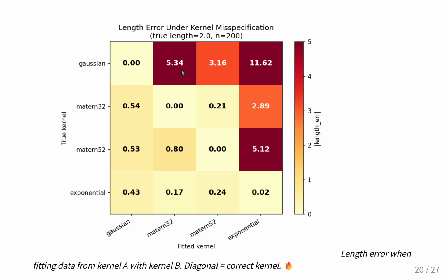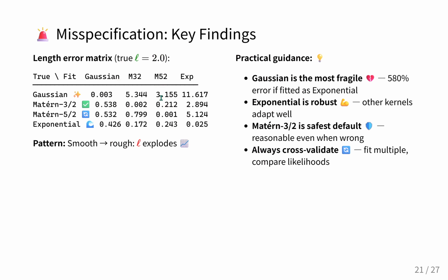So what does this all mean? Translate this mathematical failure into a real-world chip design disaster for the listener. Well, if you overestimate the correlation range by using a rough kernel for smooth data, it leads to over-optimistic timing analysis. Meaning you think the chip is faster or better than it actually is. Right, and you put it in a device, push the clock speed, and it just crashes.